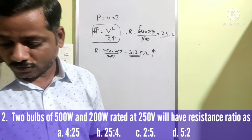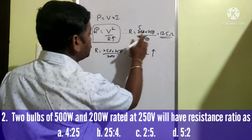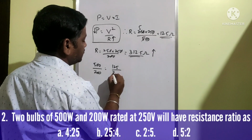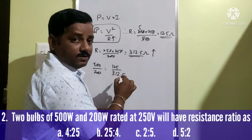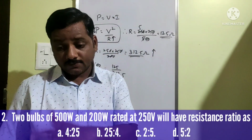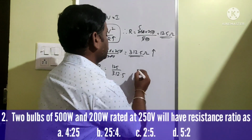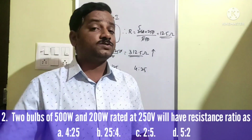Now there are 4 options. Among the 4 options, they are asking you to find the ratio of this. So the ratio can be given as 500 by 200, and the ratio of resistances will be 125 ohms by 312.5 ohms. So this is the smaller value and this is the larger value. In the options, you first find out what ratio they have given. They have given 4:25. That is possible, since first we have the smaller value. So let me keep 4:25 on hold. Then 25:4 is the reverse.